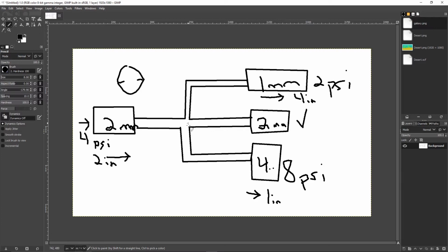And remember the other thing too. What's going to happen if I get a hole right here on your brake system or the clutch system? You're going to push the fluid, and the fluid's going to go, well, I could keep going this way and push against this, which is hard, or I could just jump out the side right here, which is real easy. And we all know it's going to take the path of least resistance, and the fluid's going to go pfft.